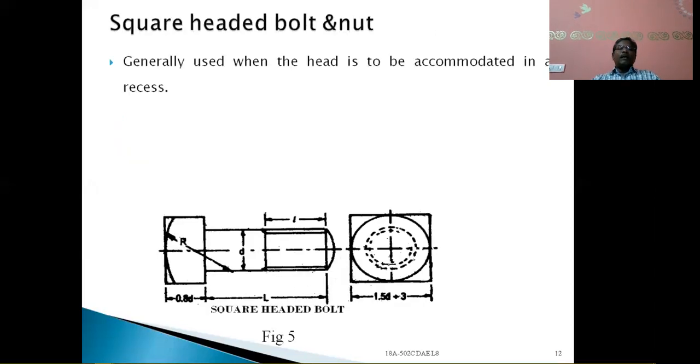So now let us see. So far we have completed only the hexagonal nut as well as hexagonal headed bolts. From flat to flat it is 1.25d plus 6, or root 3 d. In corner to corner, it is E, which is equal to 1.155 S, and the height of the nut is 0.8d to 1d, whereas the chamfer angle will be 30 degrees.